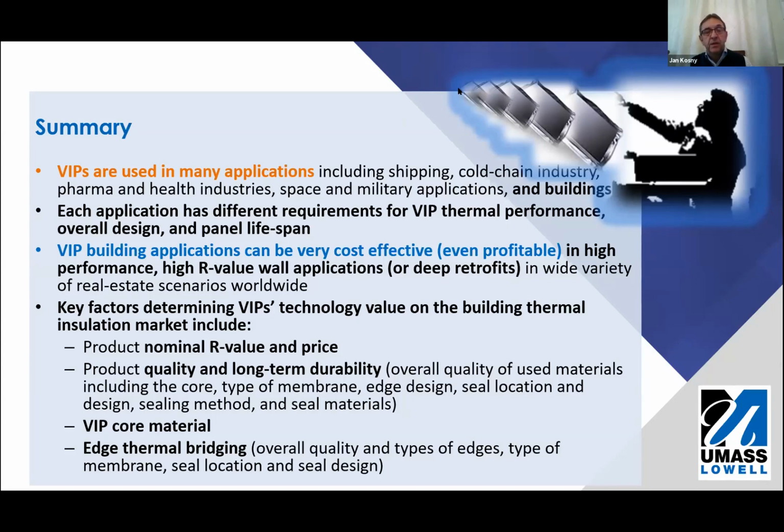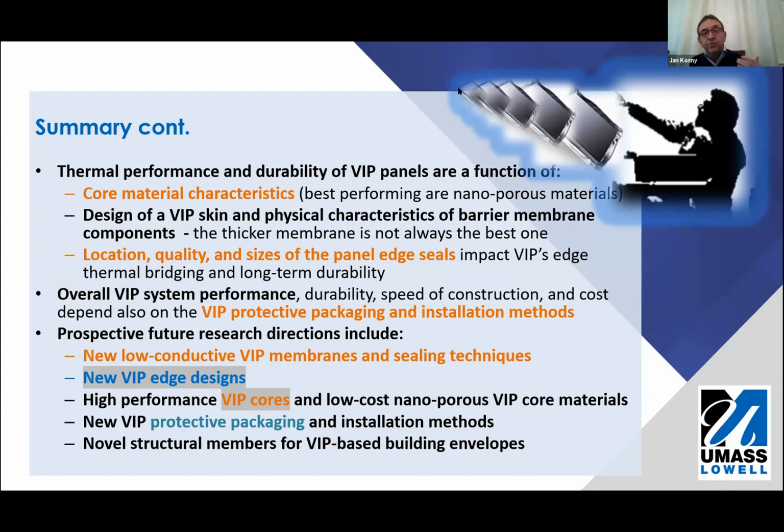I would like to focus also on one very important fact, which is about packaging of the materials. That means installation, the way the panel is installed. Packaging can reduce performance by even 50%. If a vacuum panel is incorrectly packaged or incorrectly installed, a nominal R50 vacuum panel can become R25. It's very easy. That means we are losing a lot of money.